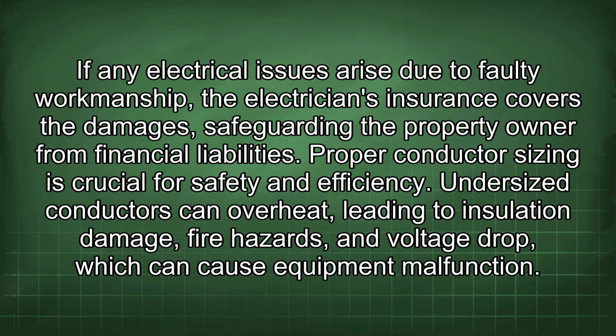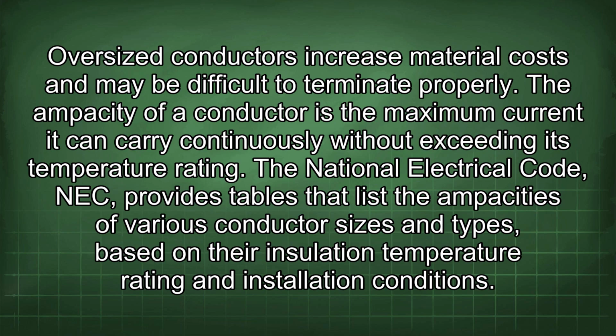Proper conductor sizing is crucial for safety and efficiency. Undersized conductors can overheat, leading to insulation damage, fire hazards, and voltage drop, which can cause equipment malfunction. Oversized conductors increase material costs and may be difficult to terminate properly. The ampacity of a conductor is the maximum current it can carry continuously without exceeding its temperature rating.